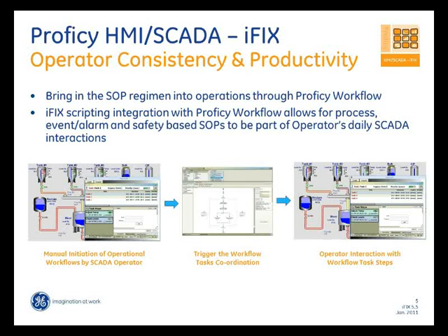If you look at workflow more as a standard operating procedure engine, which becomes part of day-to-day operations, there are just so many different tasks that each operator performs. Now, from a water operator standpoint, he could perform lockout tagouts, he could perform simple tasks such as putting certain signals off scan or inhibiting certain alarms, or there are a certain set of tasks that an operator has to do if he sees an intrusion alarm on a pump station or a reservoir. All of these are procedures that most trained operators know by default, since they have been operating on their central SCADAs for a long time.